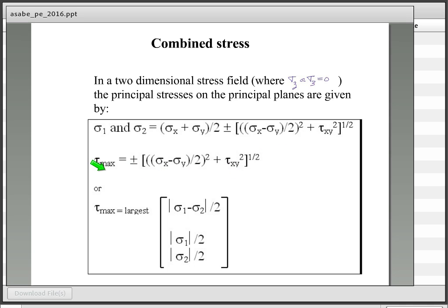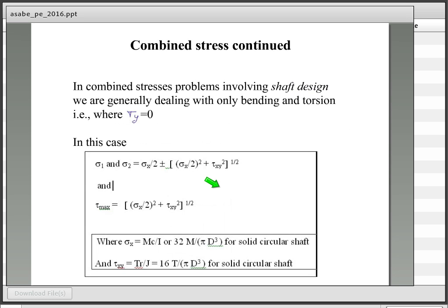So that allows us to calculate the maximum shear stress, plus or minus the difference between those two over 2, squared, is just taking the average of them, and so on. I don't want to get too deep here. I'll lose us all in the nomenclature, but hopefully you can go back and pull out your machine design reference book and look at Mohr's circle, which gives you a discussion of what's involved in dealing with combined stresses.